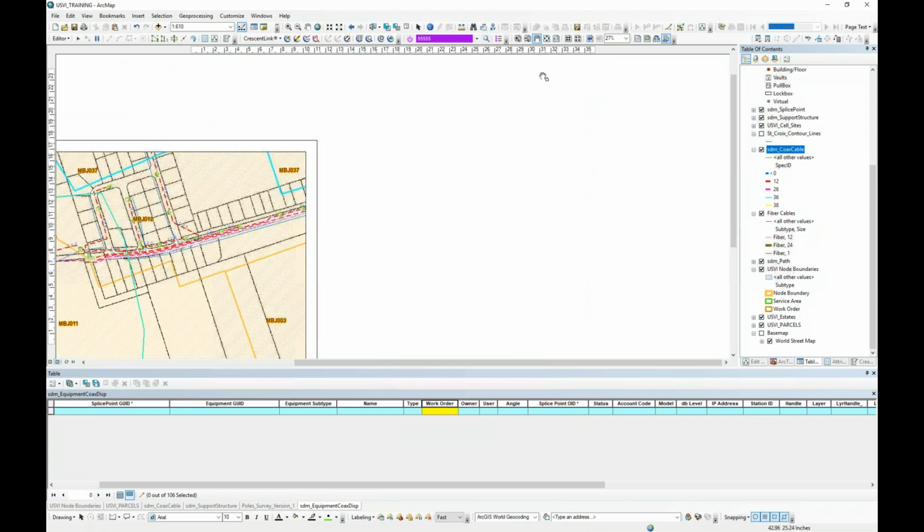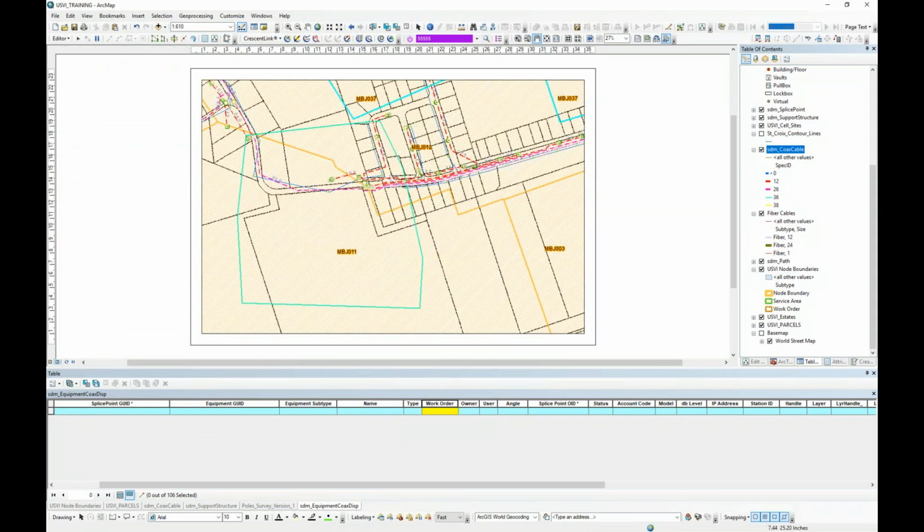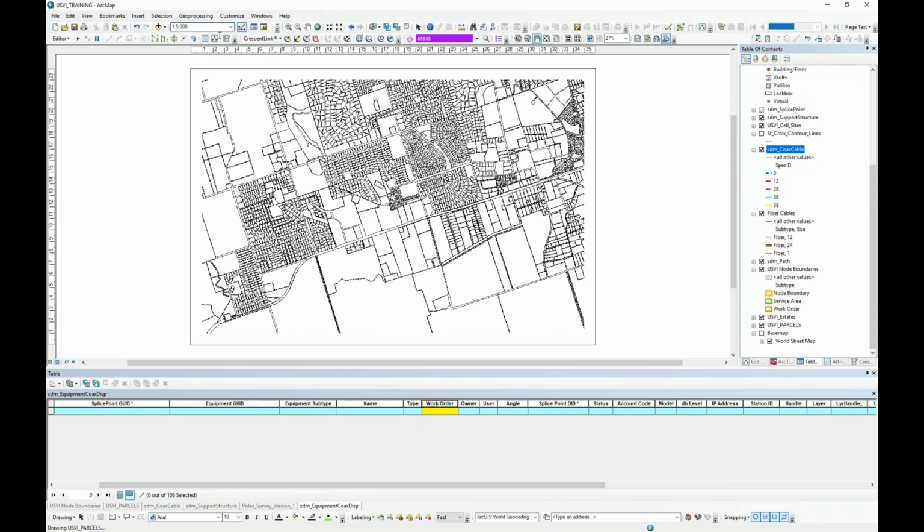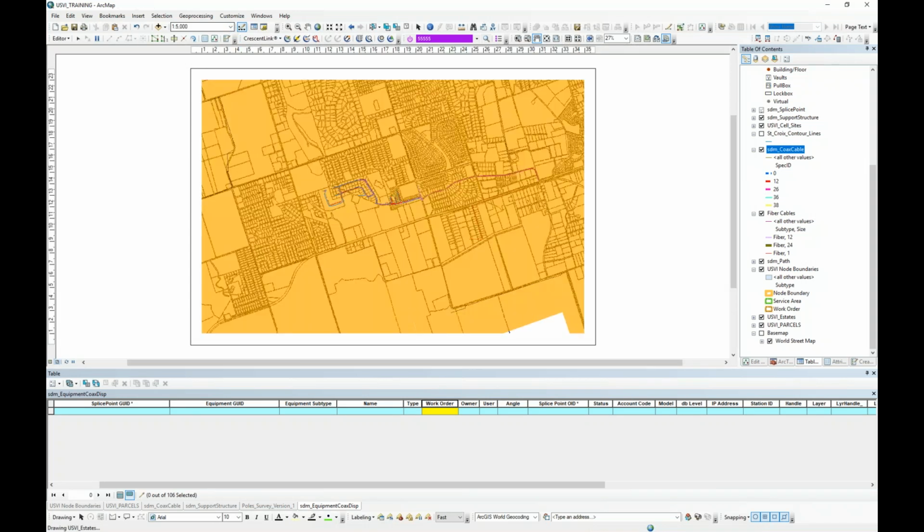Oh, also within this, this is your view. This is your elevation. How close or far away you're zoomed into. It's a ratio. Zoom out 1200. You type your number in, or there's a pick list as well. You can see how far or close in you're zoomed out or zoomed in. As you can see, the further out you get, the more stuff involved. What's that? Yeah. Our scale is usually 1 to 100. 1 to 100? Or normal viewing.